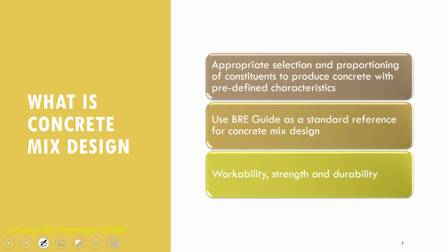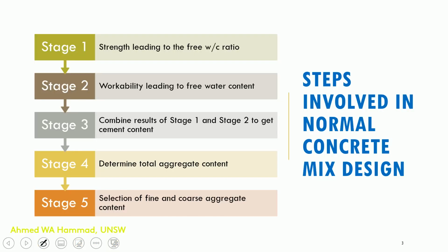mixes. Now, the overall concrete mix design process involves the appropriate selection and proportioning of constituents to produce a concrete with predefined characteristics. And these predefined characteristics would be provided to you by your client. Now, the characteristics can be in terms of the workability of the concrete mix, the strength of the overall concrete, and then the durability requirements.